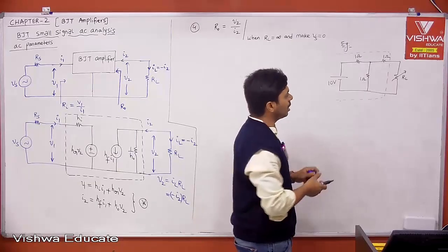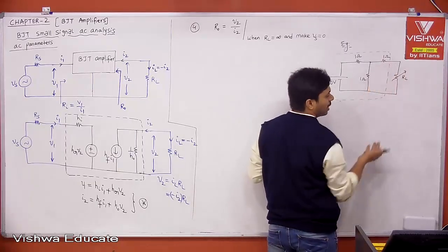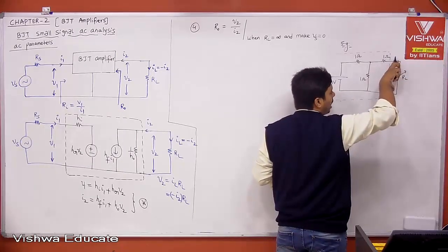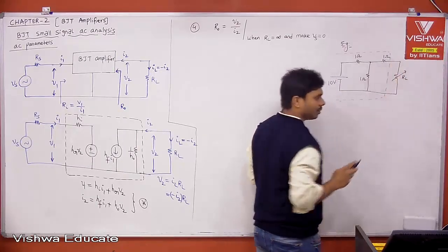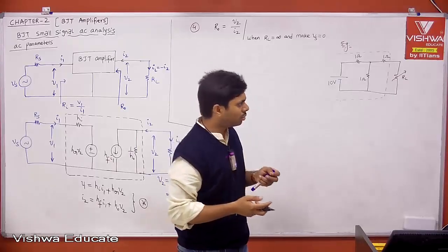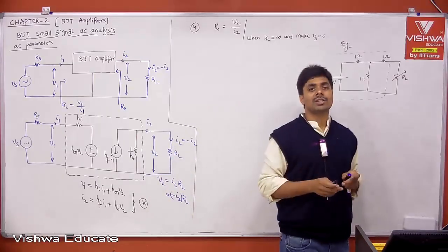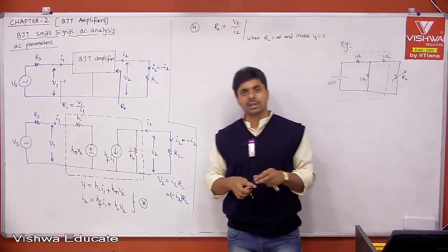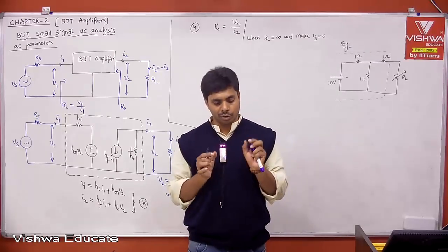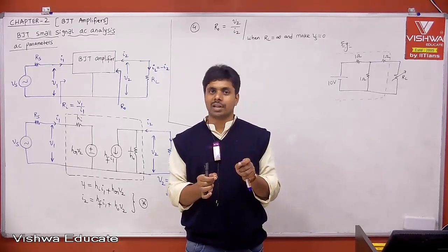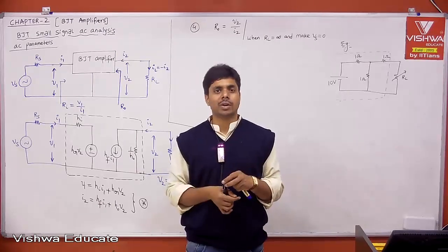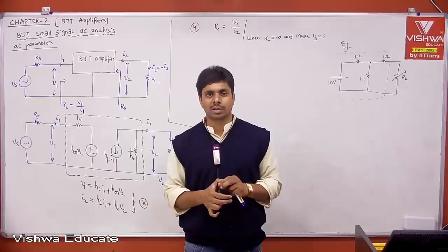The methodology is, we need to exclude the load to find VThevenin, right? Exclude the load, then whatever voltage you have from the open terminal, that is VThevenin. Okay, that is true. It is like finding the diode status. I told you, to find the diode status, we have to open the diode and find the voltage across the open terminals. If that is greater than V gamma, then the diode will be forward biased. Less than V gamma, the diode is reverse biased. I use the second approximation.